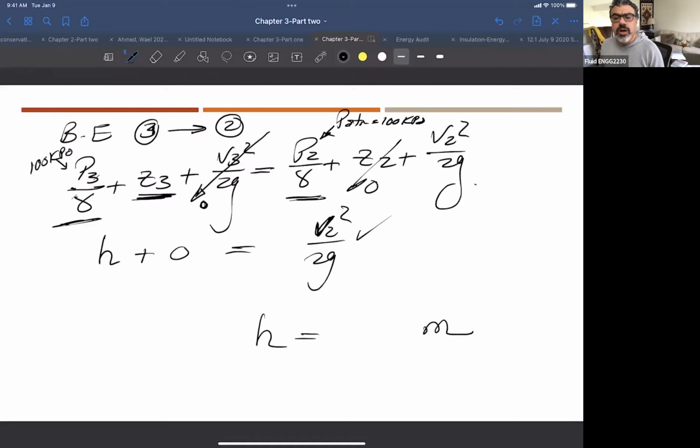It's a very simple problem, except you have to keep in mind some other information you have to know about fluids. Yes, everything is about the Bernoulli equation and the flow energy, but there is one simple piece of information from the first chapter about vapor pressure. When the liquid evaporates at the same temperature, that means the liquid pressure reduced to the point that is equal to P vapor. So this is what solves the whole problem.